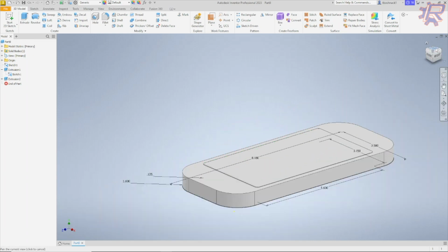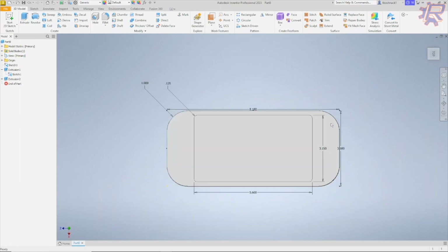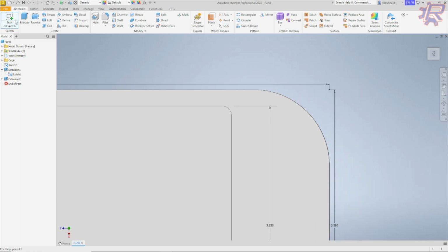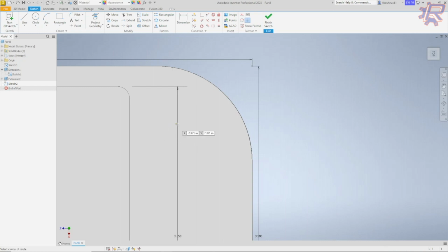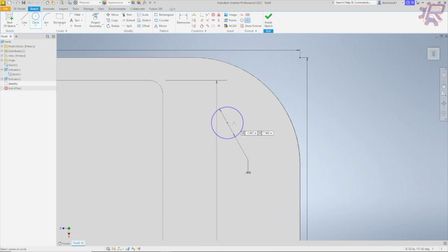Now let's make the set of buttons on the top right. So if we start this 2D sketch, let's make a button of 0.3 diameter. We're going to want to make 4 buttons all across here, but again, using the dimension tool could take a while, and it's not as intuitive as just projecting these circles in a circle. So we make another circle, a bigger one, of 0.623 diameter.